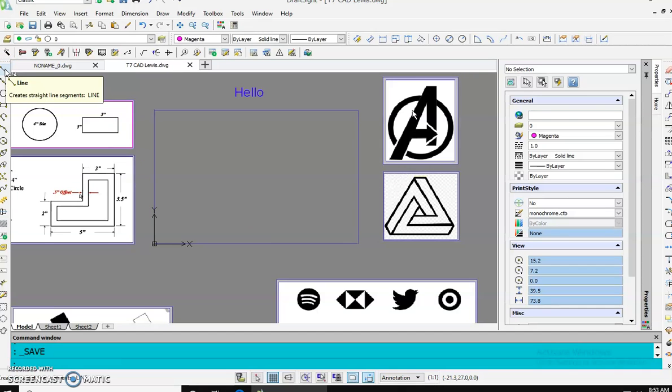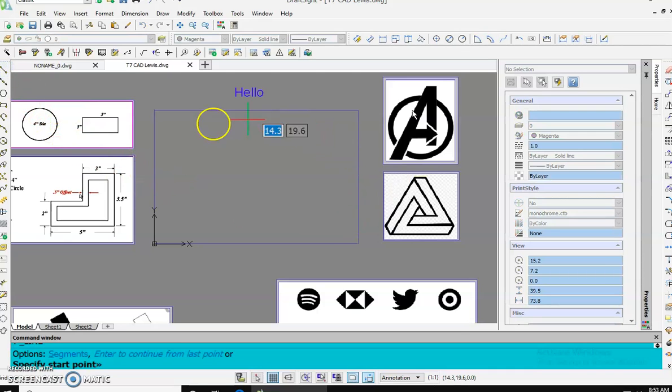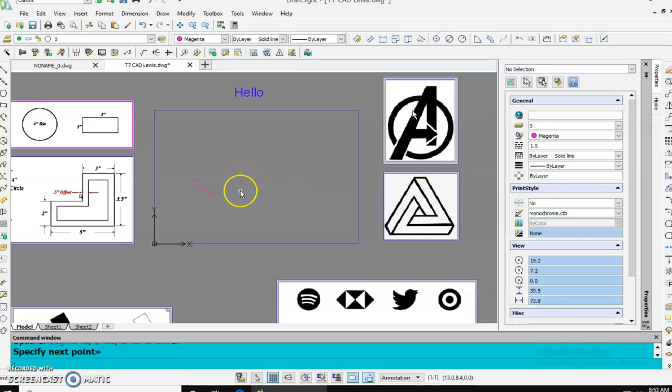That stands for line. And if you see the line, there are 2 points. Anytime you draw a line, there's a start point and an end point. That's what those 2 dots represent. Once you click on this icon one time, you don't have to double click. Inside of this box is your workspace. So I'm just going to click and drag and then press enter. Okay? And there's my line.